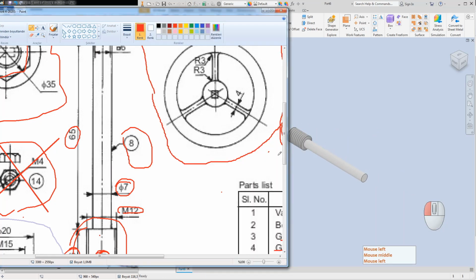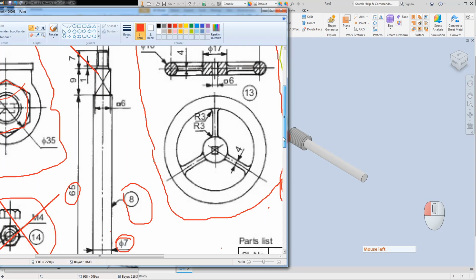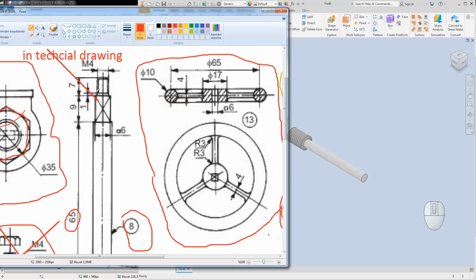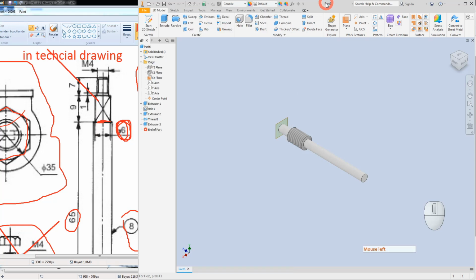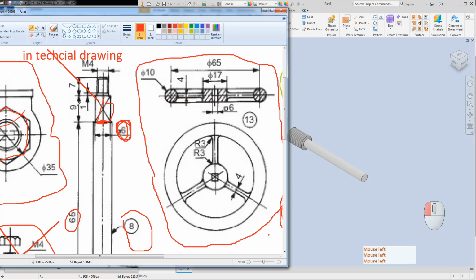This is the part here. On the top side, here we have a different sizing or different representation, like the crossed shaft. This means that in the technical drawing, we show the square portions in one section, in one view, like this. Also, we have information about the size of it. We have a 6 millimeter square, which is added to the top of this surface. I'm going to add a square portion here, which is 9 millimeter in height, on this surface.